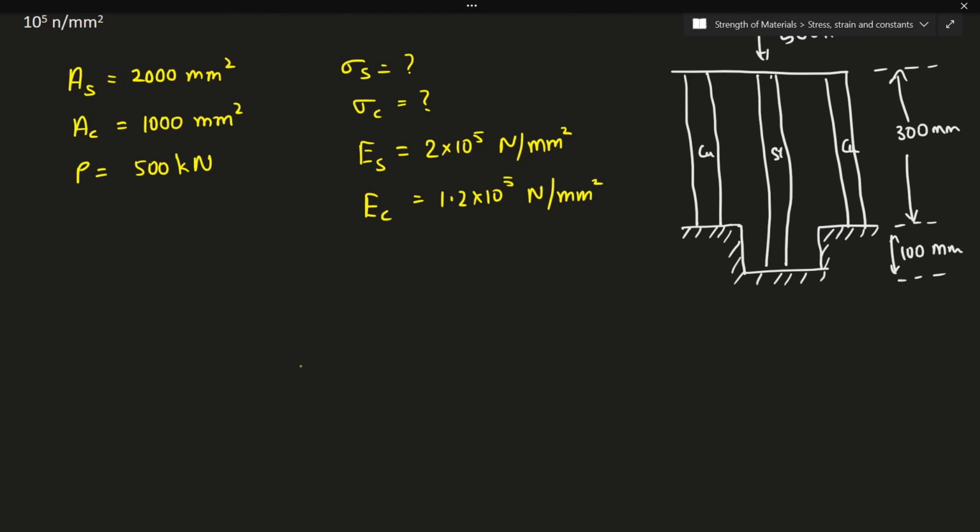Now, under equilibrium, whatever the force that has been acting on all of these particular bodies will be shared, right? So meaning that the total load that has been applied will be shared between PC, that is this column, plus PS, the second column, and again we'll have PC. Obviously, depending upon the modulus of elasticity, this load will be dependent, right? So either it might be high or low, don't know that, right? So P will be equal to 2PC, load taken by the two copper columns, plus the steel column, right?